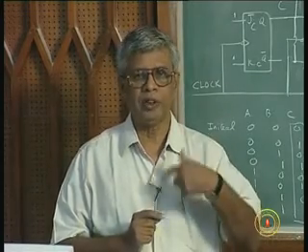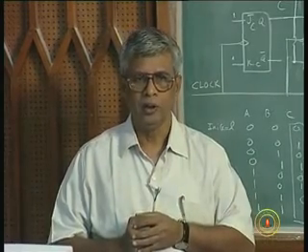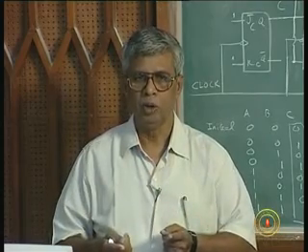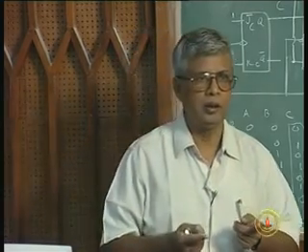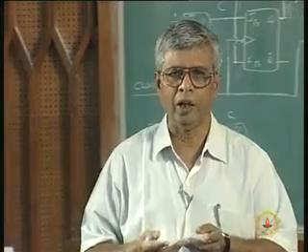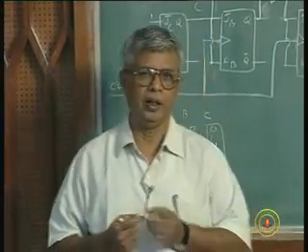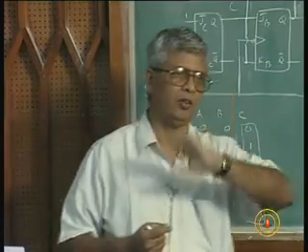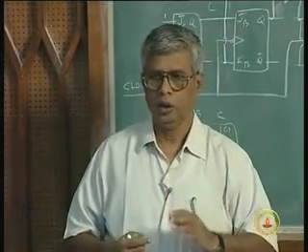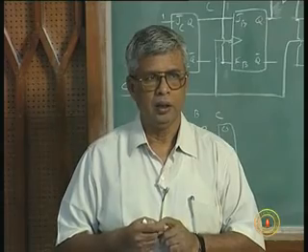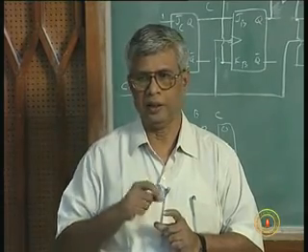This is the concept of a synchronous counter, wherein the clock is given to all the flip-flops, and the change is controlled by the outputs of the flip-flops. Earlier we tied J and K of all the flip-flops to 1. So every flip-flop toggled, but then the clock was delayed.